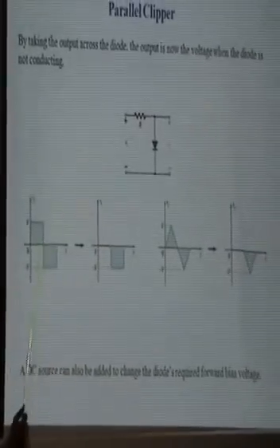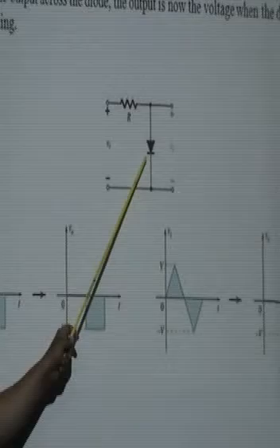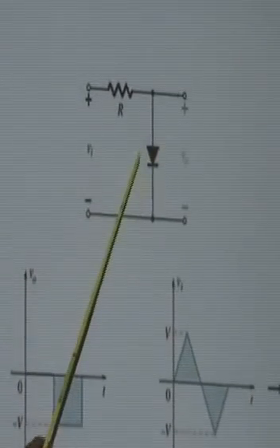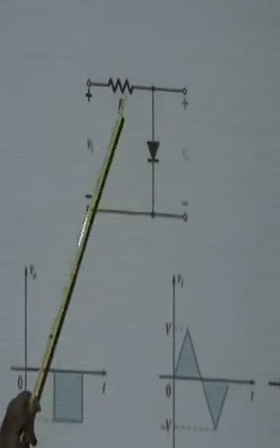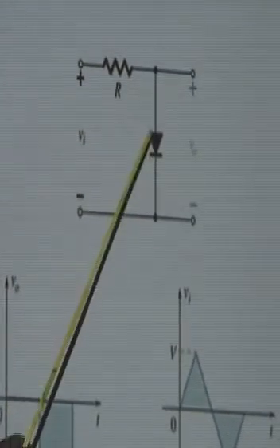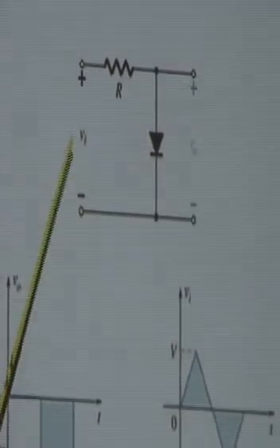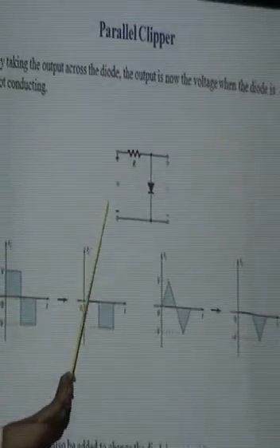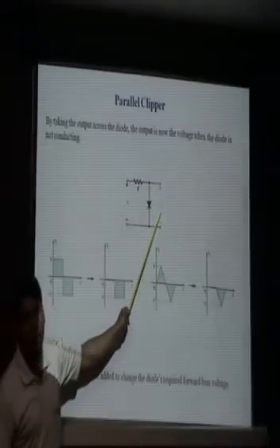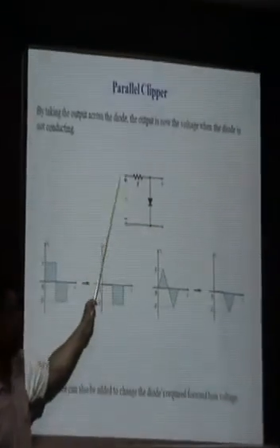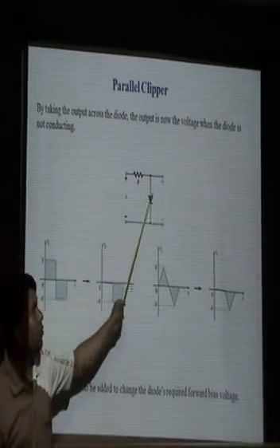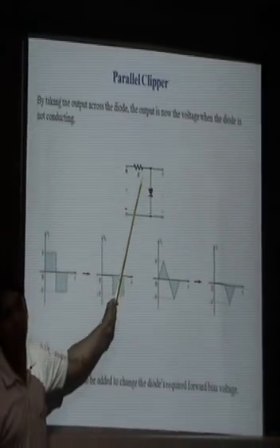Now for the negative half cycle from pi to 2 pi, the terminals are changed. Now the diode acts as an open switch. Means that if the diode is here, okay. If the diode is not here, then it is also okay, because it is now an open switch. So if we apply Vi across these terminals, then it appears directly at the output terminal, because we just forward the waveform from this terminal to this terminal, because this is an open circuit, so nothing is connected.